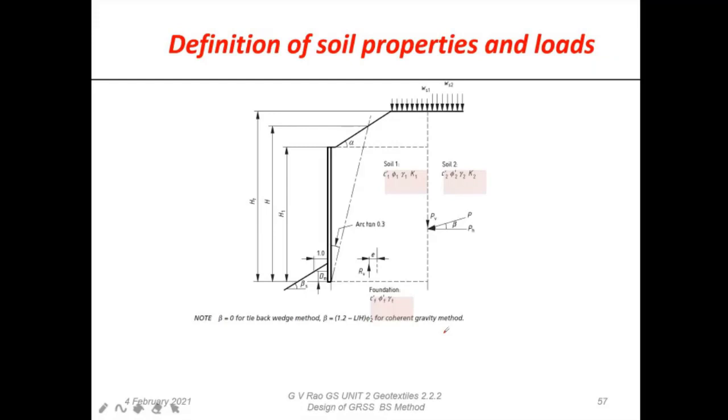The other most important thing is what I call a differential sketch in this entire code now. Remember that we are going to deal with three kinds of soils in the same wall design. One, of course, is very obvious. It is the foundation soil. Foundation is not our choice, basically. So we are interested in finding out, obviously, what are three things now? We're interested in finding out the effective parameters. We have to find out the C prime, phi prime, and effective gamma for this foundation soil.